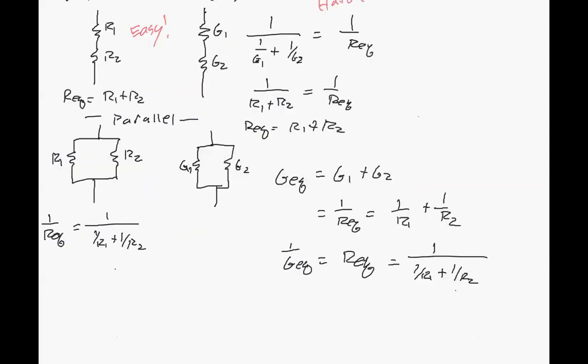And we've got all the same relationships. And the same thing happens for impedance, where Y, the admittance, is 1 over Z. When you see parallel circuits, it's often easier to use conductance and admittance, at least for equations. When you're putting in values, it may or may not be easier, but when you're working with equations, it's almost always easier to just go straight to the easy way to solve for parallel or series, depending on the combination that you have.